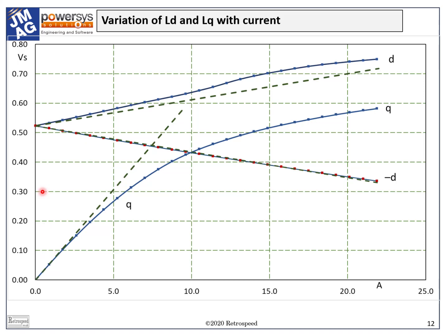So the d-axis curve begins at zero current with the d-axis flux linkage due to the magnet, psi m, and as we apply current in the positive direction, the flux linkage increases. The slope of this curve is practically constant and not very large, indicating that LD in this particular IPM is quite low and not greatly affected by saturation.